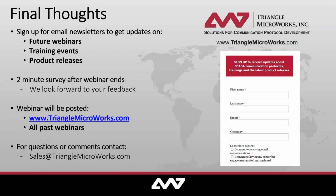Okay. All right, I think the last question, Christoph, this one will be for you. For SAT using 61850, do you normally make functional tests using secondary injections or repeat simulation test with all devices connected, and then another phase using primary injection? Looks like you're mind reading. I was just about to answer that question. I think that at the end of the day, it depends on the philosophy of the utility. But I would assume in most cases, the SAT testing of your protection and control system is done with secondary injection, primary injection, and testing all your CTs and VTs. That's typically independent, and it's not so easy to handle.